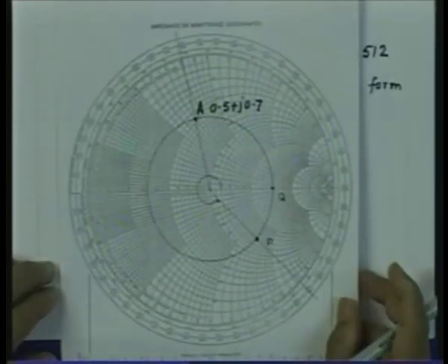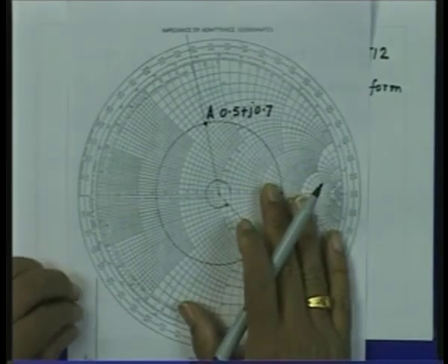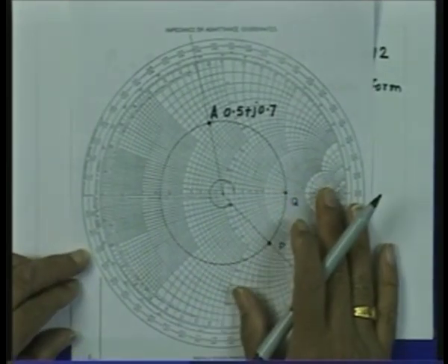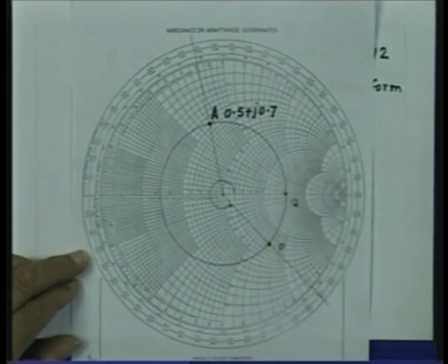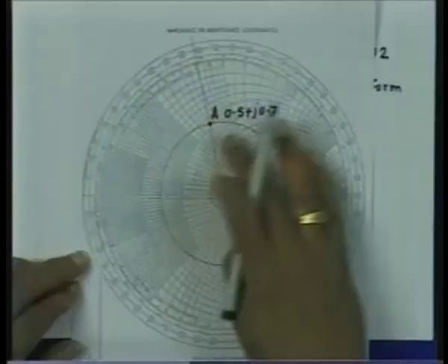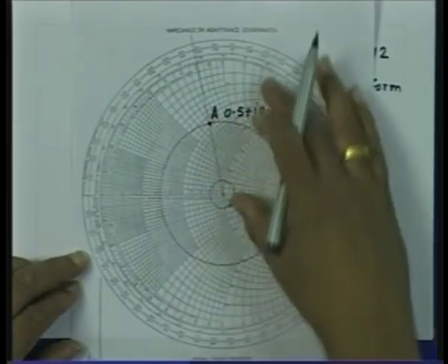So, the point which was made, that the use of the Smith chart makes the calculations of transmission line extremely simple, can be seen here. If we had used the analytical expression for the impedance transformation, we would have to do the complex calculation. In this case, just by drawing the constant VSWR circle passing through this point, we can just read off the values for the reflection coefficient, impedance, VSWR and so on.